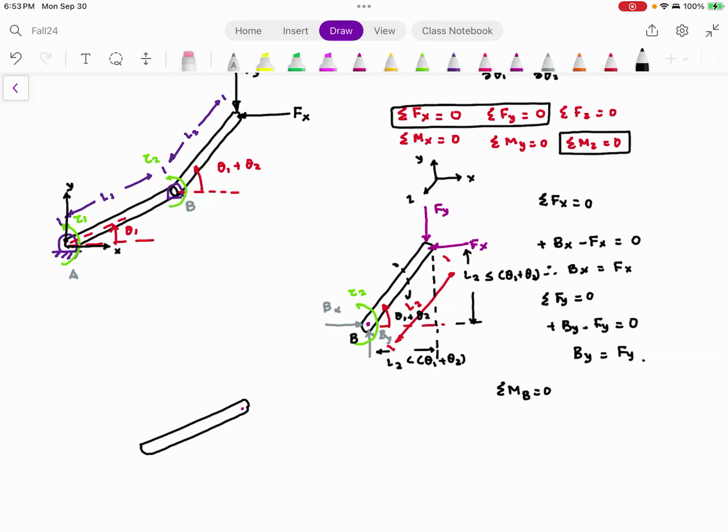And that is actually very important because when we solve for forces, the same convention will be used. Curl your fingers in the direction of the movement. The thumb is going towards negative z, which means that moment is negative.